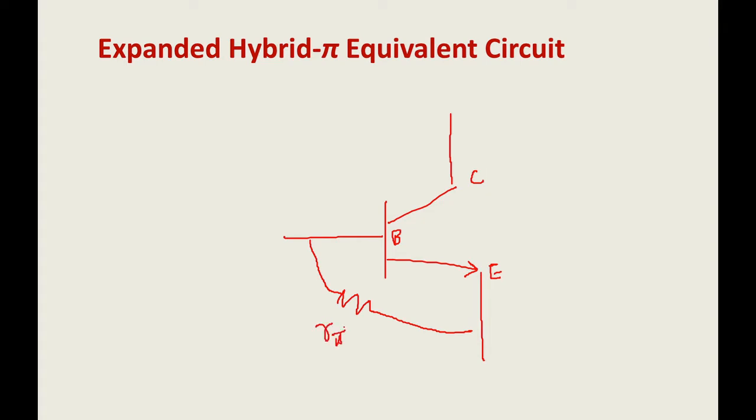First I'll give the idea of how to understand it from the transistor, then I'll teach you the exact expanded model. Let me first draw the transistor. You know that in between base and emitter is forward bias, and in between base and collector is reverse bias. So between base and emitter you have a forward resistance, that is called R pi, and a forward capacitor, that is called C pi. Understand that pi is nothing but B dash E, and mu is nothing but B dash C.